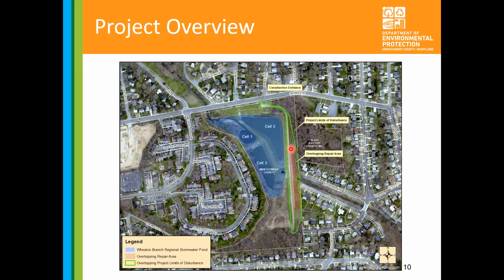Basically, concrete was placed over top of them to reinforce these baskets. So in 1988, this spillway was added with gabions on top and what we call Inca mat, or geotextile, on the slope of the dam.